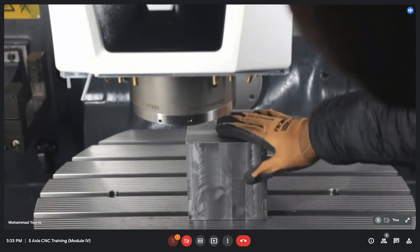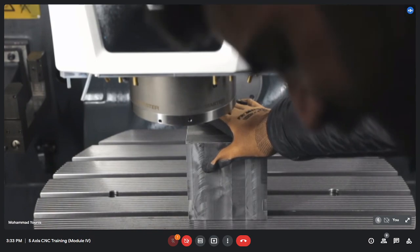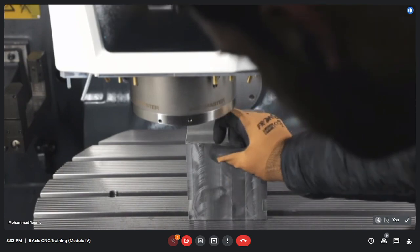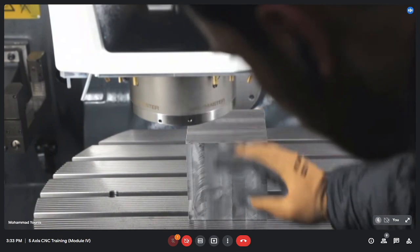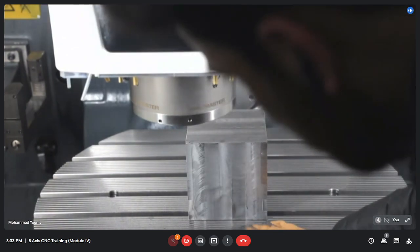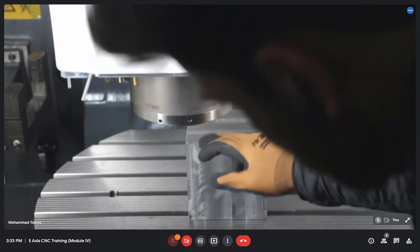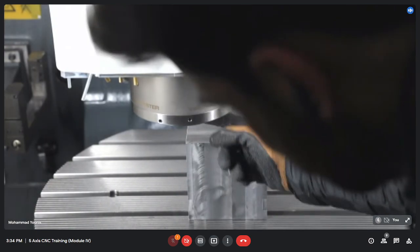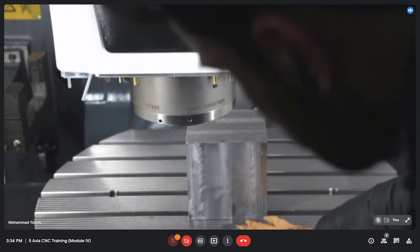This plane, or I can say this top face, is the origin point for the z-axis. So here I have already set a value of 50 mm. That's why the machine has provided the position to the spindle as where it is presently. So this is actually the 50 mm gap here.